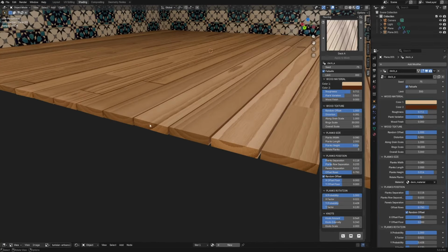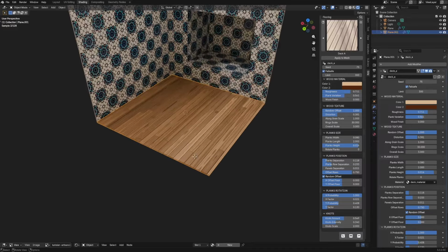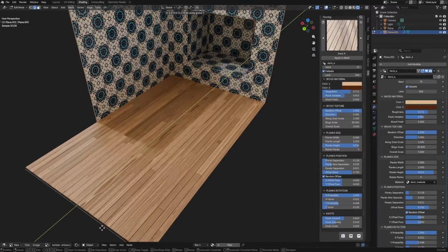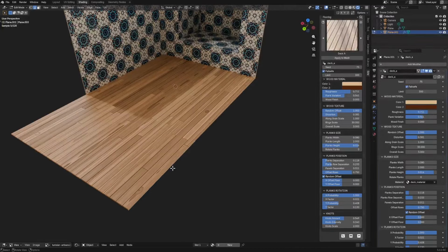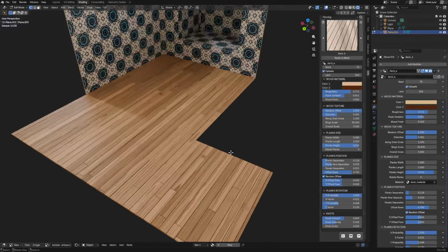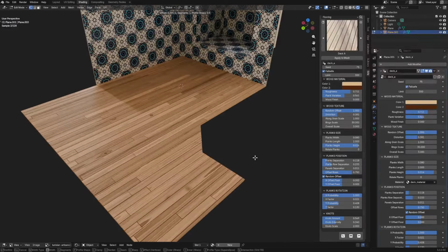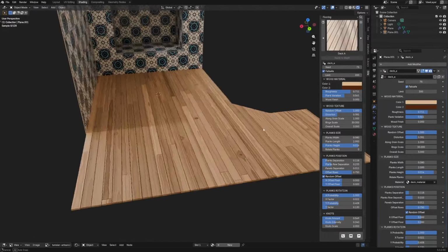With the wood, you can see the sides, how they have a different texture, even if it matches the one on the top. You wouldn't have this with a PBR material. Again, this is non-destructive. You can keep editing. The only condition is that it is flat. Extrude Y. We can take this one, extrude X. I can take this one here and Ctrl-Shift-B, bevel it.